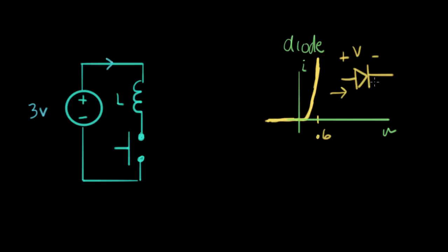So I'm going to take advantage of this diode device to help me with this problem I have over here with the current. And the way we do that is we hook up a diode pointing in this direction here. Pretty distinctive. But anytime you have a circuit that has an inductor in it, so it's a solenoid or a motor or a relay, this is a way you can protect the devices driving your coil. So let's look at what happens here when we push this push button down and let it go again.